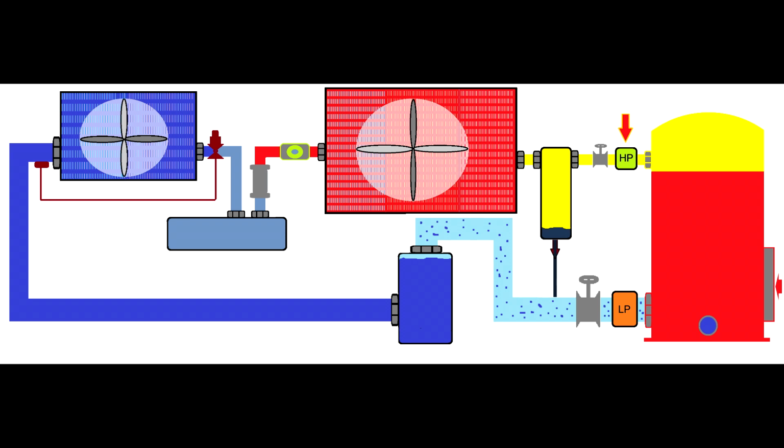The oil separator will be overwhelmed, and the worst scenario is the liquid goes into the piston cylinder, and as everybody knows, liquids are not compressible. Imagine when the piston tries to push the liquid with that speed towards the condenser. What will happen? You will destroy compressor valves, you can damage the piston, and